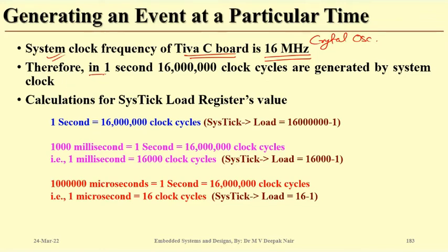Because it is connected to 16 megahertz, in 1 second the microcontroller can count up to 16 into 10 to the power 6 pulses or clocks.